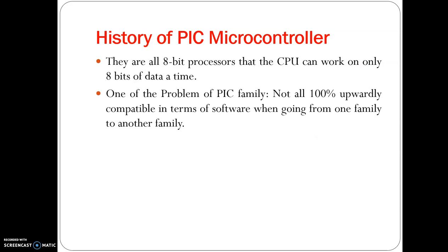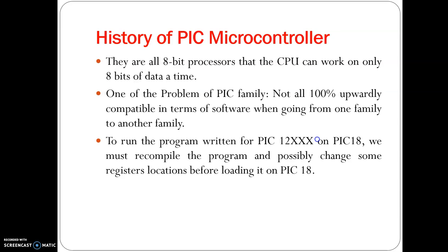Now, this particular PIC family has one problem, and that is not all of them are 100% upwardly compatible in terms of software when going from one family to another family. So what exactly is meant by this? Let's take one example. While the PIC12 and PIC16, which have the 12-bit or 14-bit instruction format, the PIC18 instruction is 16 bits wide with many new instructions.